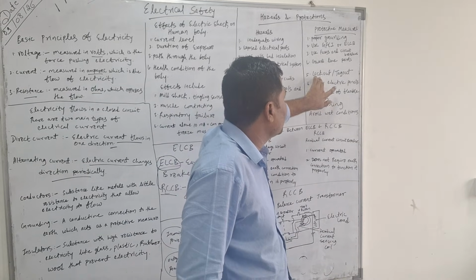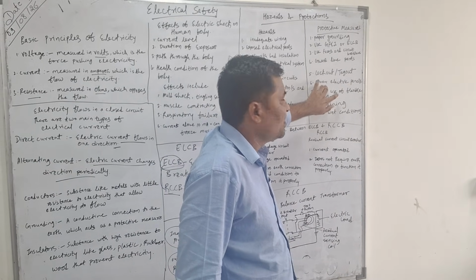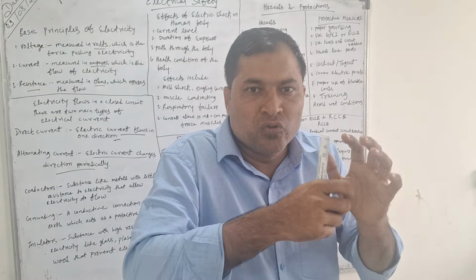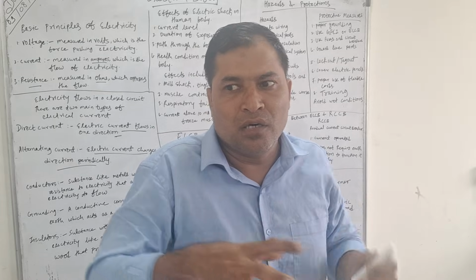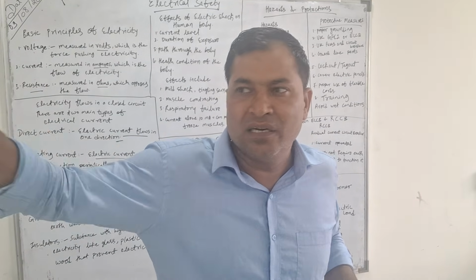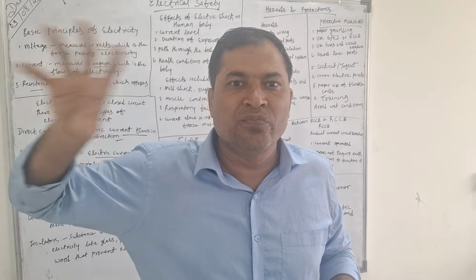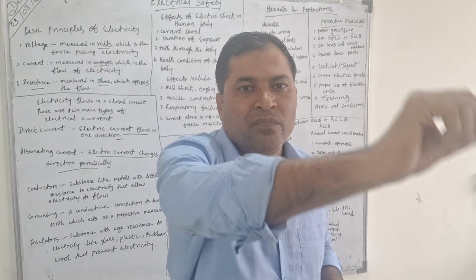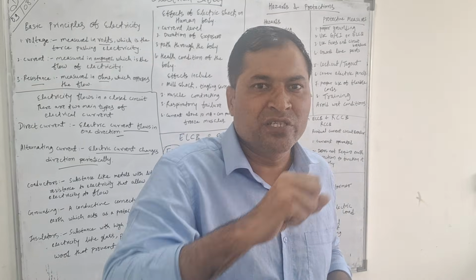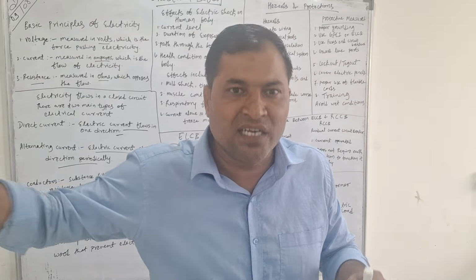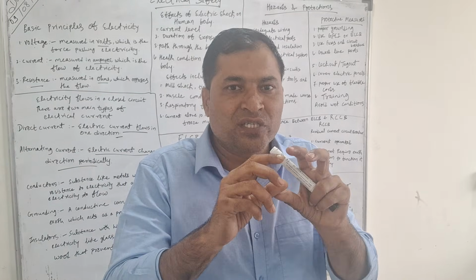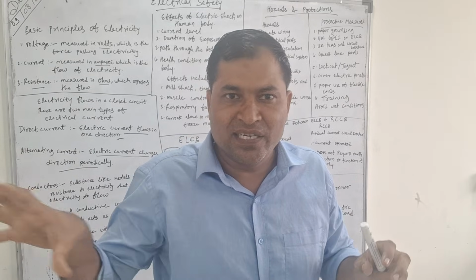Lockout tagout system is also very important. Any electrical panels should be in a properly closed condition, with lock and key, so that new workers cannot go there and touch that part. You have to take permission from the electrical officer, and only then go there and operate on the electrical wires. In the lockout tagout system, you have to use tags: unauthorized people do not enter this area.